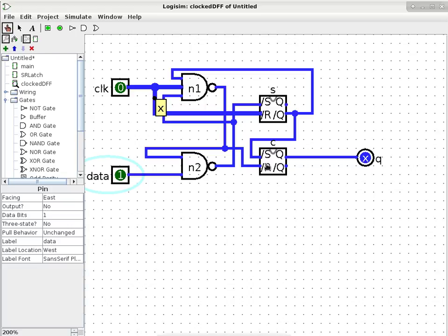Is that okay? So now we look at the transition. Okay, so this is the big difference between a clocked or edge sensitive D flip-flop compared to a regular D flip-flop that is not edge sensitive. So what we want to do now is to say, what happens when clock goes from 0 to 1? Okay, what happens at exactly that particular moment? And we can just assume data is a 0 for now, and we are saying, okay, we're transitioning clock from 0 to a 1. So we want to analyze what is going to happen at exactly that moment.